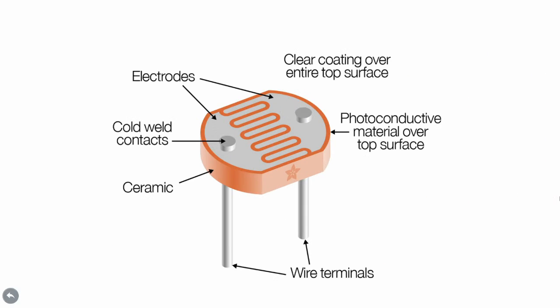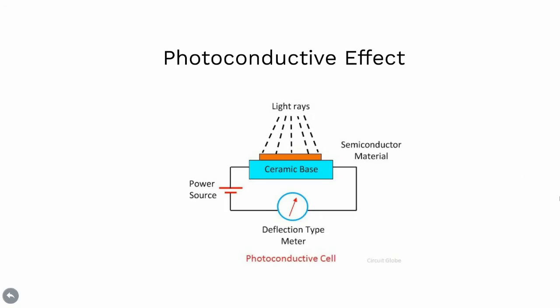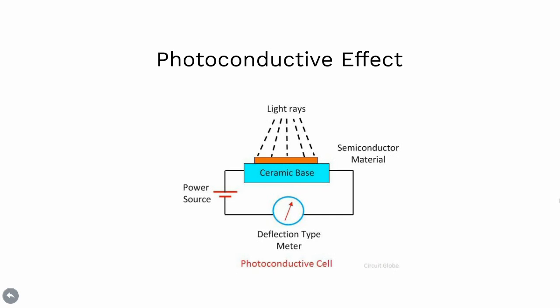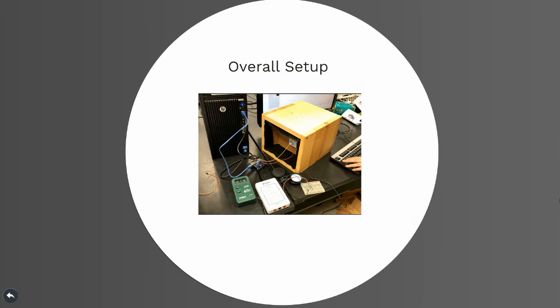Most photocells are comprised of a thin strip of cadmium sulfide. Cadmium sulfide has photoresistive properties that allow its resistance between its terminals to change depending on the light intensity it is exposed to. The photoconductive effect is a phenomenon where emitted photons from a light source excite electrons in the valence band of the cadmium sulfide to the conduction band. This allows for charge carrier movement with sufficient excitation, thereby decreasing the resistance between the photocell terminals.